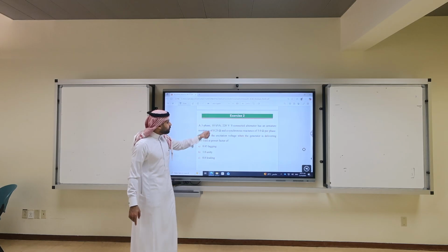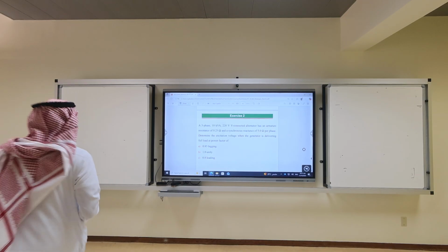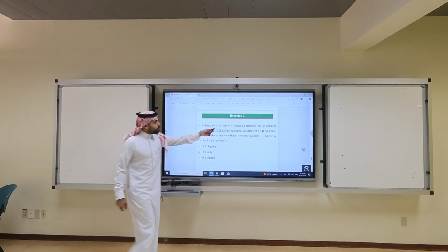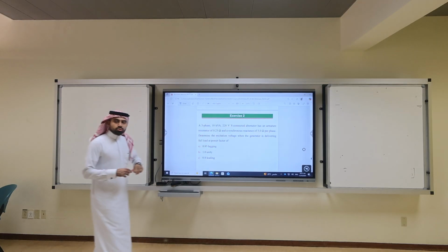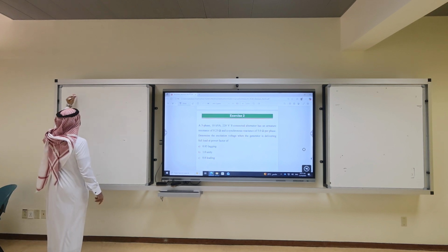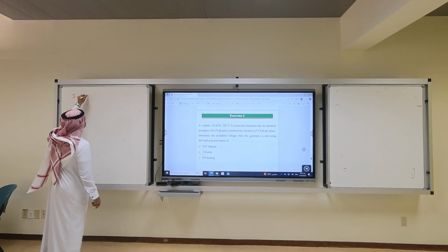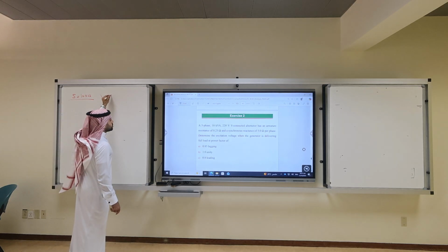So here, am I allowed to use this S? Yes. So what is the S? Is this a small generator or big generator? This is 220 volt, okay? 220 volt, and it's 0.1 MVA. 0.1 MVA. So what is the S? 10 kVA.